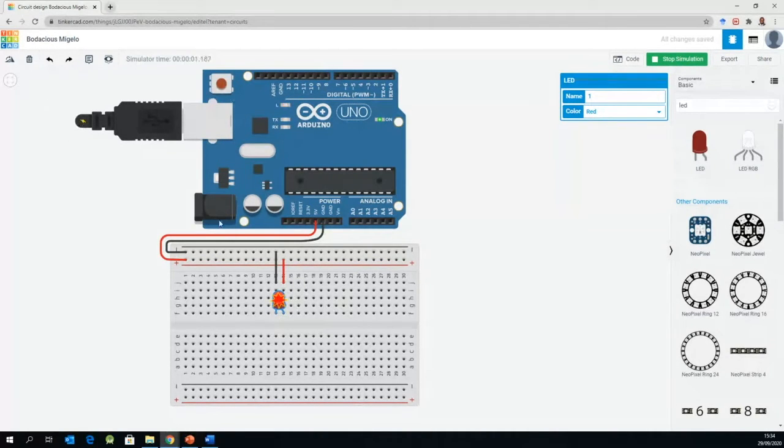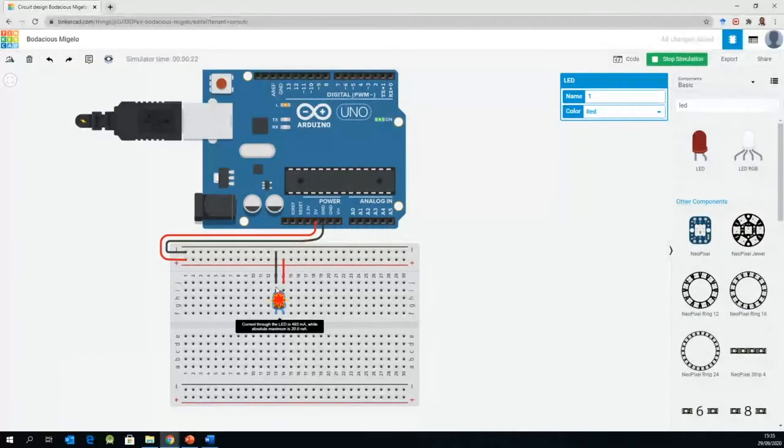It shows that there is power connected, but it shows that my LED has blown. So basically, if this was in the lab, I would have destroyed an LED. What happened? The current going through the LED from the 5 volts is too much for the LED to handle. As an activity, you can find out why this current is too much, and that goes to Ohm's law, V equals IR. In order to reduce the current going through it, we need something called a resistor.